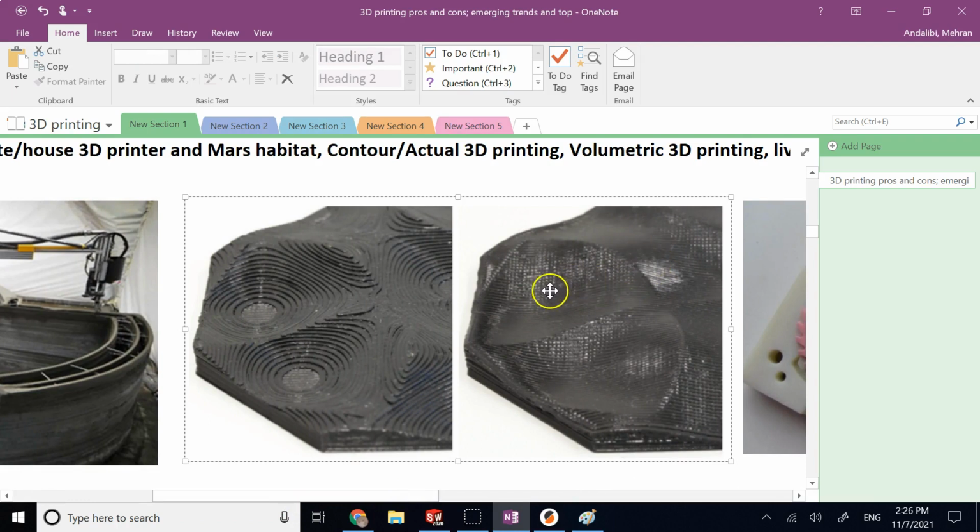The plastic can lay out something at a specific Z on the XY plane, and then without finishing that XY plane and going to another Z, it can immediately move to another Z level and lay out plastic. So while it is working, it can move along X and Y as well as Z at any time point, okay? And it's not limited to staying at a fixed Z level before going to the next one.